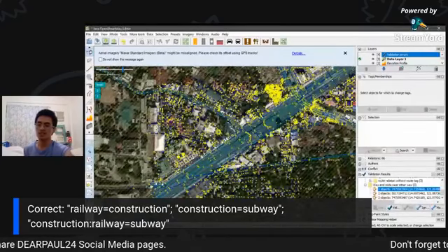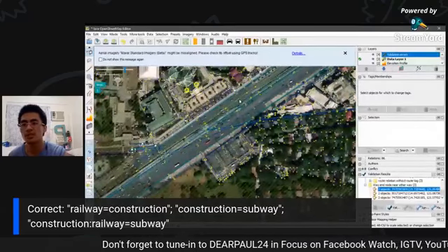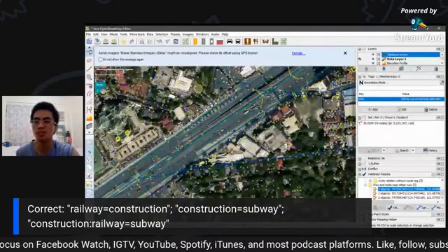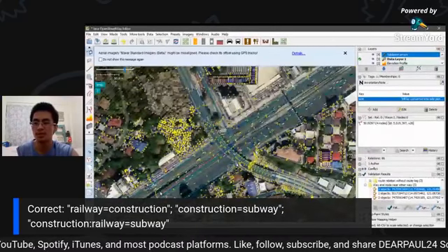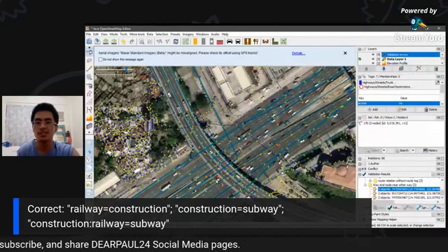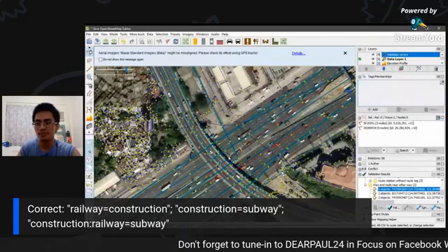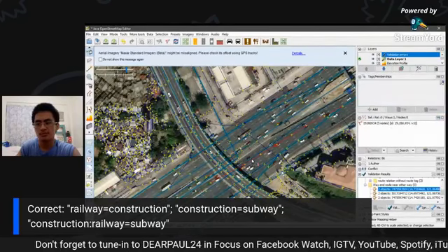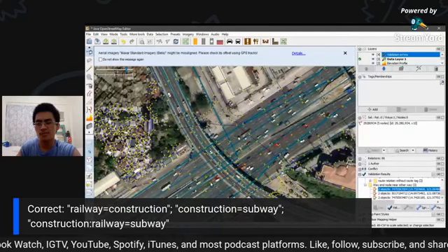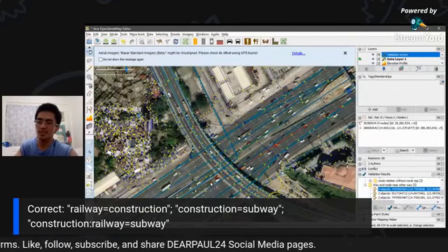And let's use some remnants of those demolished structures. This and this has to go. Hold Shift plus click, then Alt plus J, and there you go.